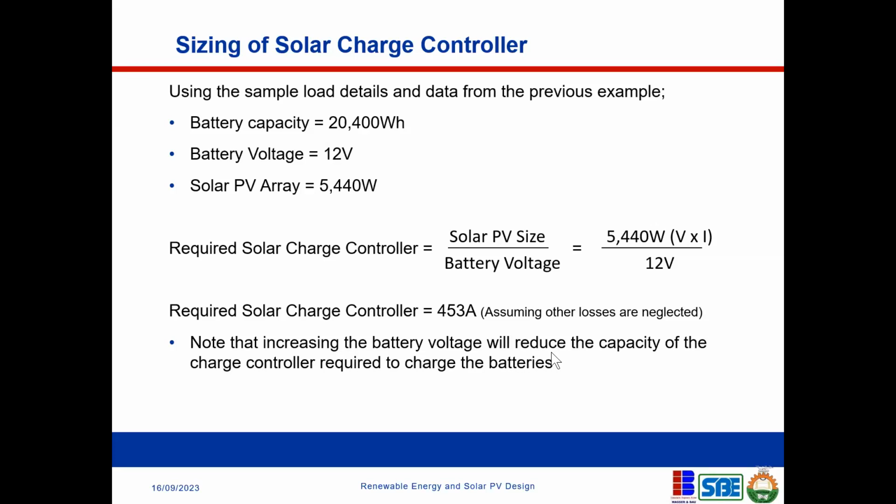Of course, continuously charging the battery could put the battery in danger. In fact, it could damage the battery, and that's the reason why we have charge controllers. We have battery management systems to monitor the charging voltage that is considered to have the battery fully charged. It cuts off the supply of current to the battery.